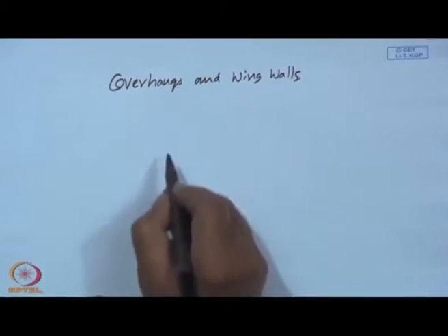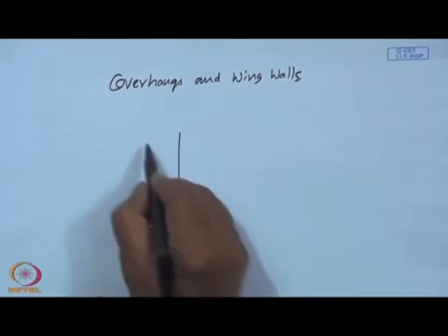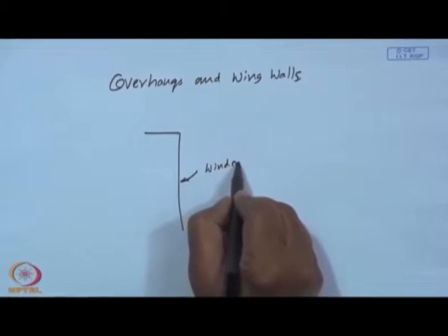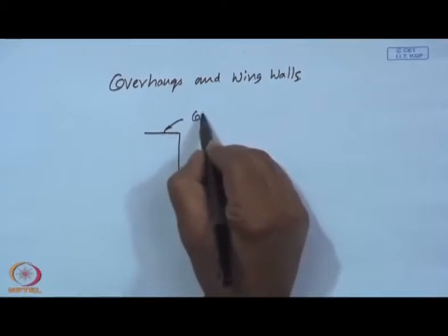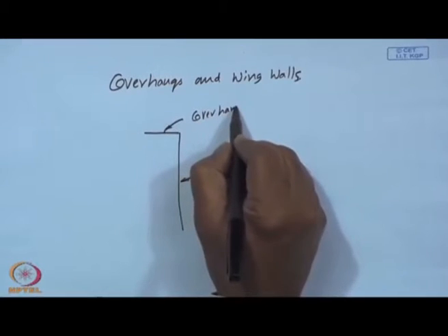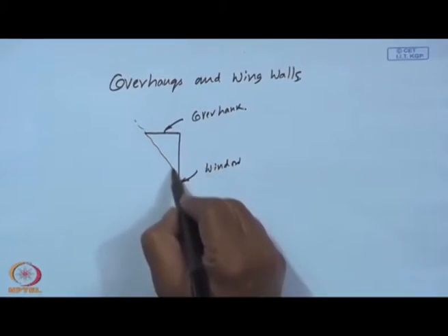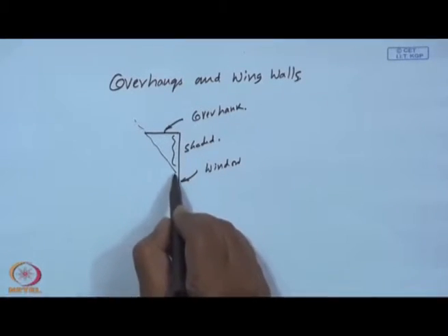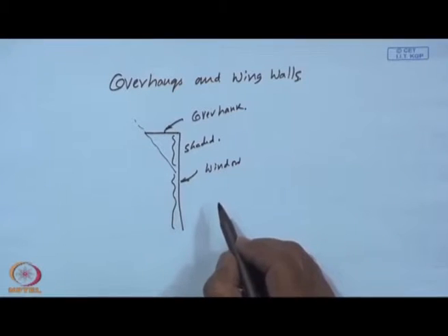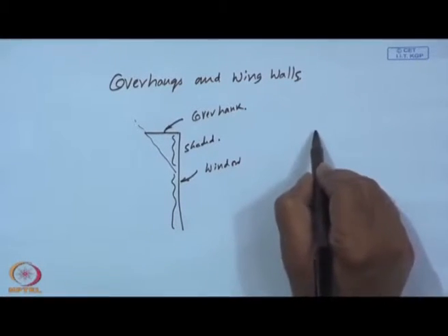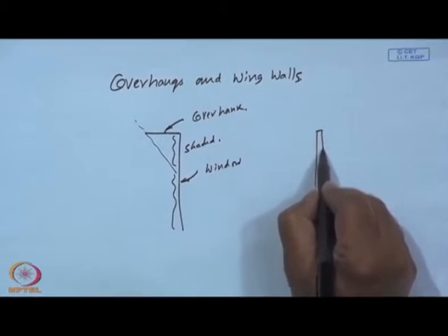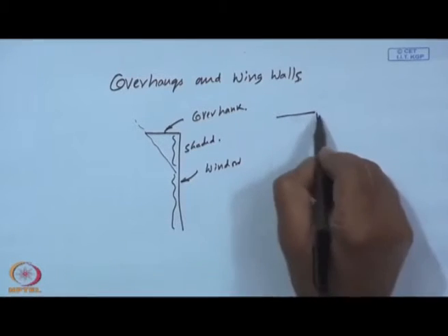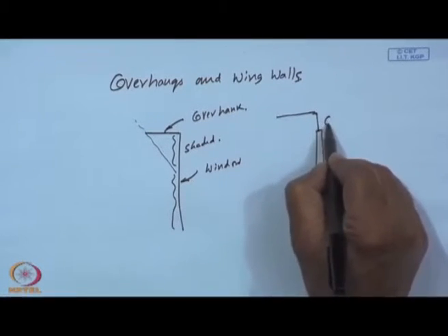The whole idea is, if you have, in the end view, this is the window and this is called the overhang. So, this will not let the sun shade it over a certain area; the remaining part can be lit. And of course, you may also have a window of certain height, then a wall, and the overhang may be after a certain gap G.